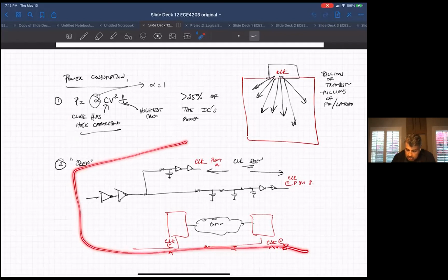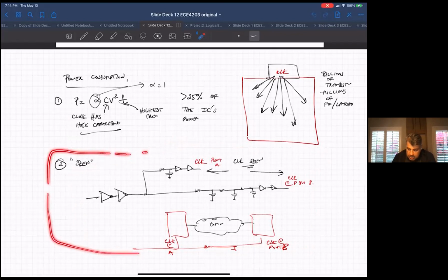And it turns out they will also take a disproportionately large percent of your design effort as you fight this thing called skew, which ends up being a big, big problem on every single design, because it's just hard to distribute these clocks. They're running really fast. Your product engineers, your marketing people will always make sure you're running at the absolute fastest you possibly can,